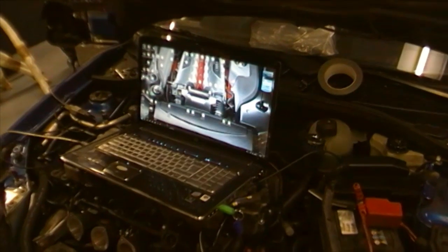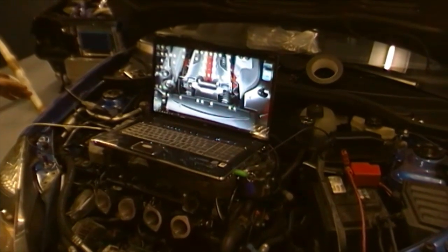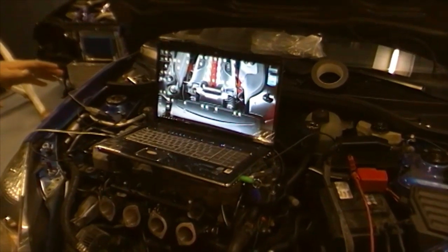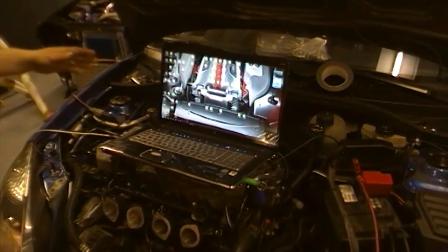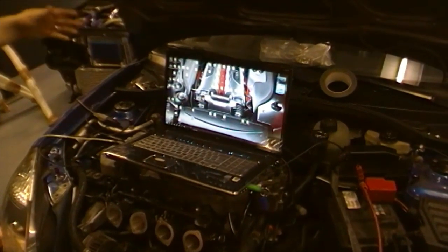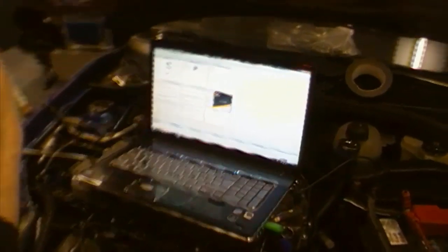Everything hardware-wise is connected and we know the engine turns over, so we're in a position where we can connect to your ECU with your laptop computer. Once you've downloaded the GEN Tuner Lite software from the website using the instructions which we will provide, you need to open your software up, and we're going to turn the ignition on. So now the car is powered up, and we go up to ECU and then we go to connect.